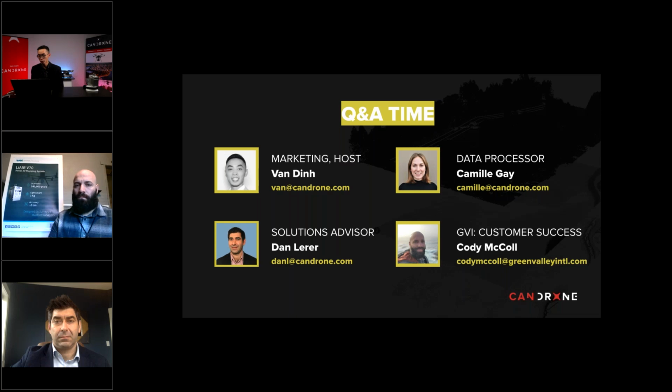Okay, thank you, Camille. The next question from Eddie again: does DJI Terra do a good job on its own with the Boresight correction, the strip alignment? Yes, it does a pretty good job. There still sometimes is a bit more noise since there's a high point density, so DJI recommends running an outlier removal algorithm on it. Once you have your LAS file from DJI Terra, you can bring it into LiDAR 360 and use the outlier removal tool to minimize any of that fluff.